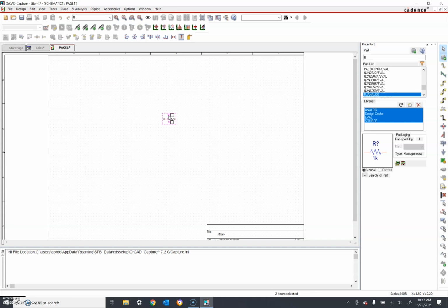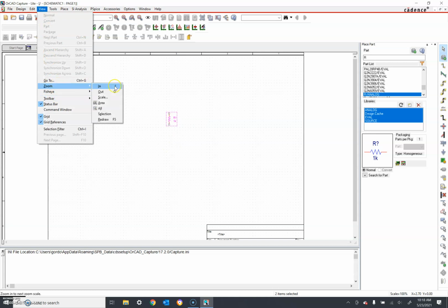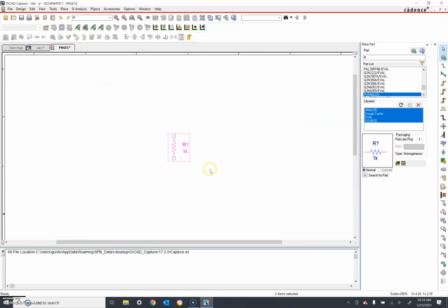Now I can make the resistor vertical. See how the whole thing is highlighted? It's all pink here. I'm going to click escape here. If I click R here now, see I flip the resistor around. Horizontal, vertical, horizontal, vertical. I'm just hitting the R key on my keyboard. I'm going to leave it in vertical position here. By default, excuse me, let me zoom in a little bit on this here. By default, it's given an identification of R1, and it has a value of 1 k ohm.